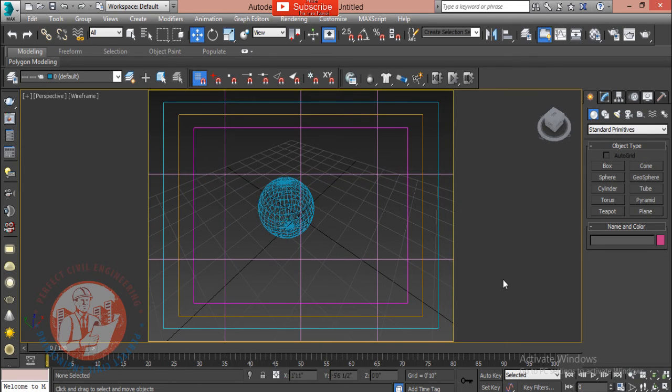The Safe Frames panel of the viewport configuration dialog box lets you define several safe frame options, as shown following. Live area marks the area that will be rendered, shown as yellow lines. If a background image is added to the viewport and the match rendering output option is selected, then the background image will fit within the live area.